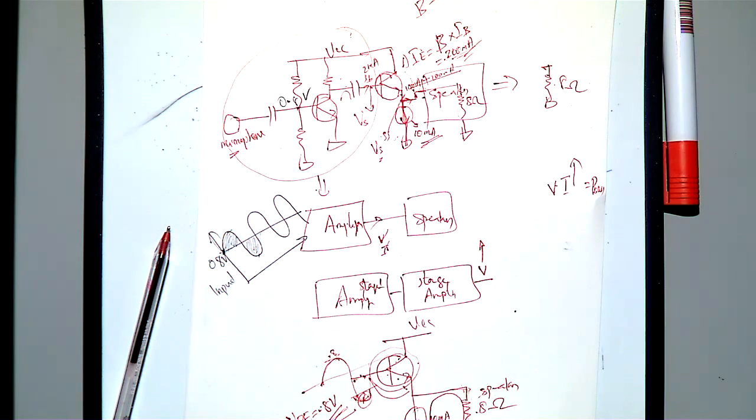And then VB, when you connect to this V in, what is VB? VB minus VE. What is here? This is a PNP, so we will be talking VEB. So that is equal to V emitter minus V base. Here what is happening? If you connect one more, instead of the current source, now you got one more transistor, and then you are connecting input to the base of both the transistors.